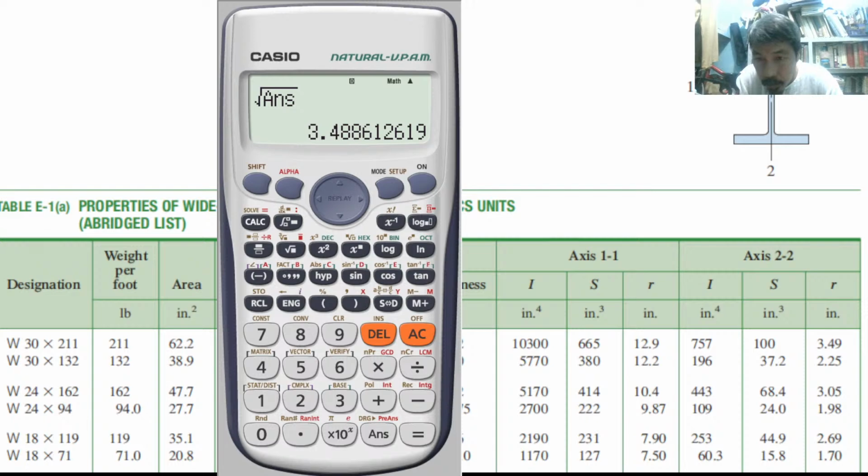Angles 1, 3, 4. So the 4 angles will function as flanges and then provide the web. Use a plate to function as a web. Another built-up section, similar to this one, but you have another plate on top and bottom.